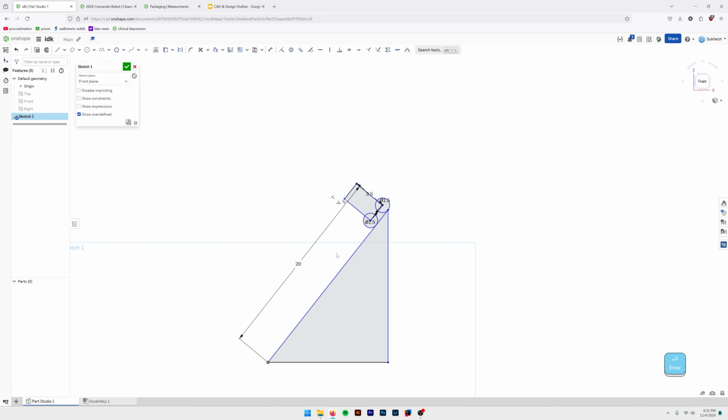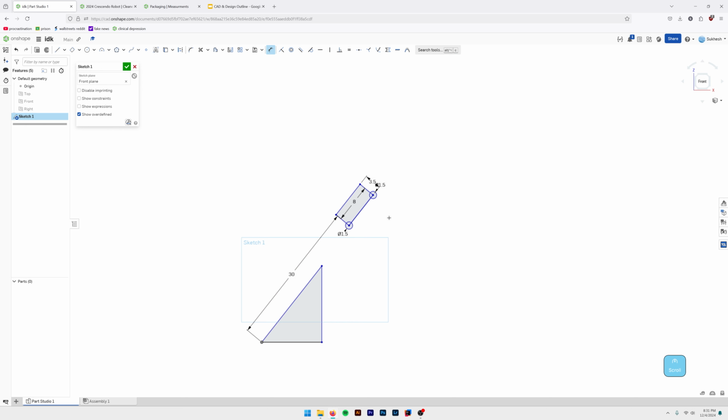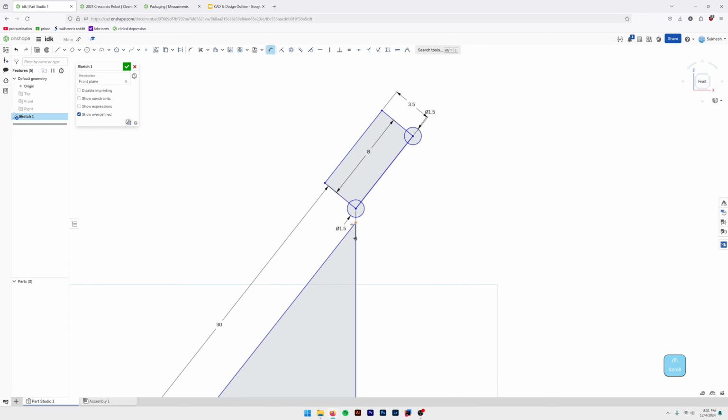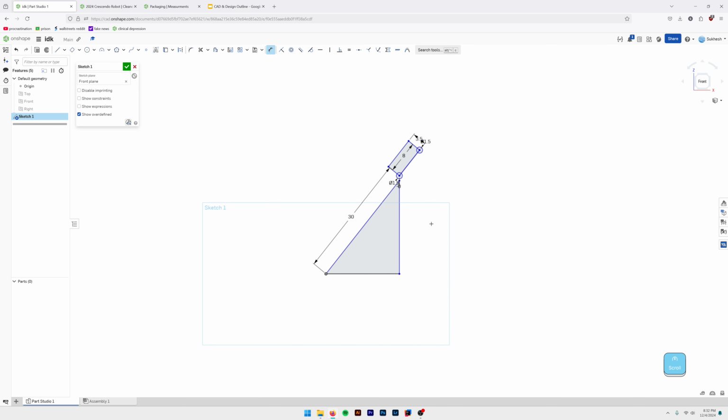Now it's just the back that's moving, right? So dimensions create these relationships, and then we can change these dimensions to do stuff for us. It really just comes down to understanding constraints. It's actually pretty cool, something definitely worth learning. If I make this 0, that won't work, because that would not work. But this one would. Like this. But yeah, that's basically variable sketching in a nutshell.